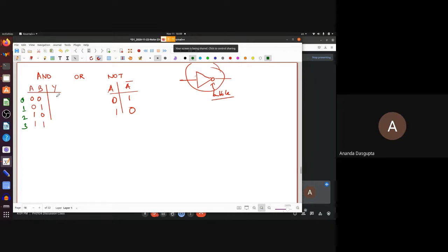And we would like to write down the output corresponding to this. I hope everybody remembers that this is called a truth table, simply because Boolean statements which you have written down as zeros or ones could also take values, or would equivalently take values, false and true. And here A AND B essentially has this property, that it is true only when both inputs are true. So, or high only when both inputs are high, or 1 only when both inputs are 1. A OR B, on the other hand, again, if we do it with only 2 inputs, will look somewhat like this.